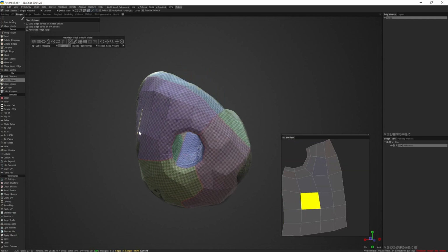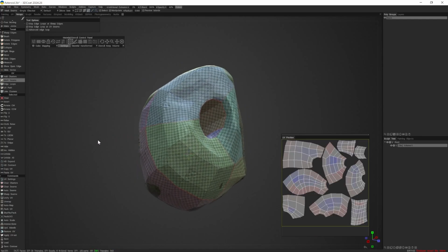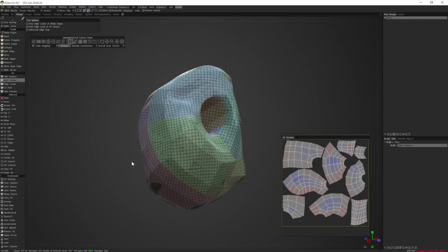We have a high poly sculpt. It already has texture paint on it, so even the texture paint will be baked down to the low poly mesh, in addition to the normal map, which is great. But we could further do texture painting on that low poly mesh after bake as well. Or we could save all our texture paint to the low poly mesh after bake if we wanted to. I just like to do it before, especially if I have a fairly high poly sculpt mesh.